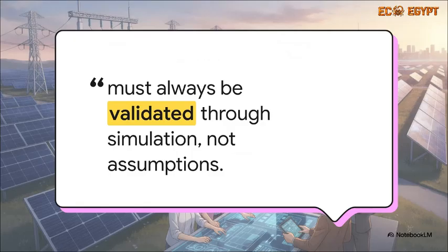I actually want to pause for a second on this core engineering philosophy right from our source material. Sizing is never just guesswork. Math is your map. It gets you in the right territory, but software simulation tools like PVsyst, well, those are your compass. You absolutely must mathematically validate your string lengths against those extreme temperature coefficients, and then you simulate the whole year to make absolutely sure your chosen DC to AC ratio is going to generate the financial returns you're expecting.